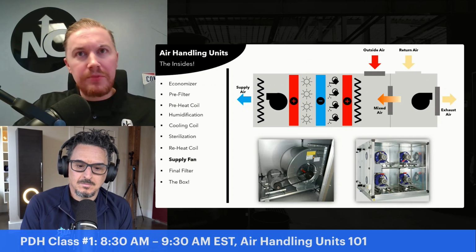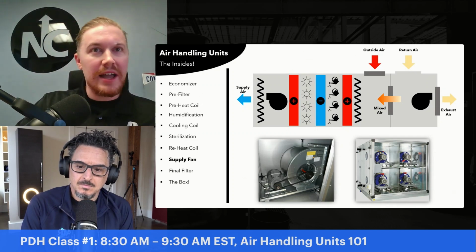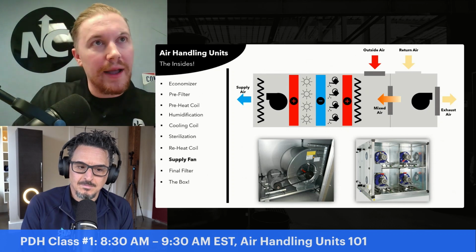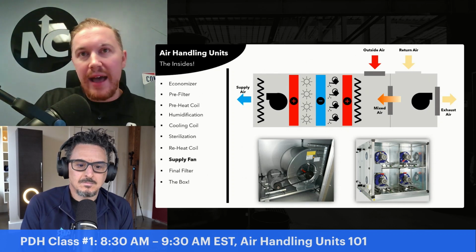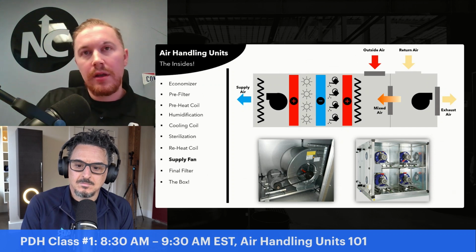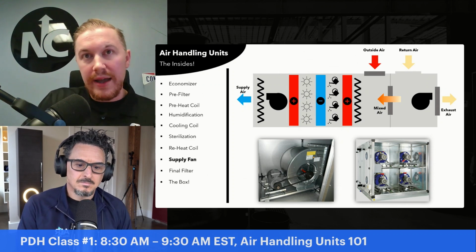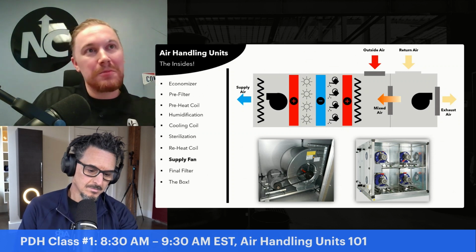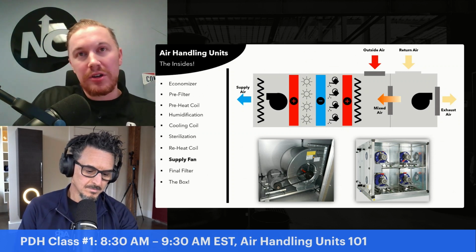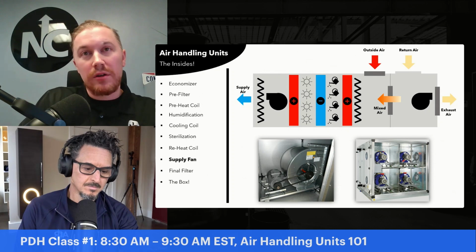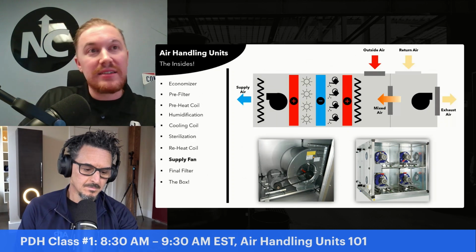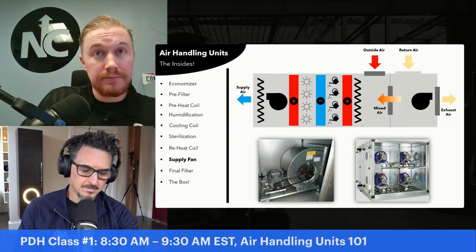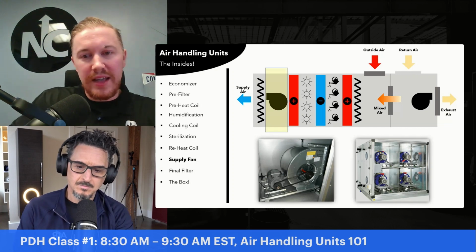Okay, we've got fan options. In yesterday's world, we had a lot of centrifugal fans that were belt driven, 1 or 2 per air handler. And in today's world, we have an array of fans, typically like we see on the bottom right, where we're reducing the density of that horsepower, spreading it out over a number of fans, and creating a serviceable and easy, redundant fan system. Okay. We're towards the end here, guys.